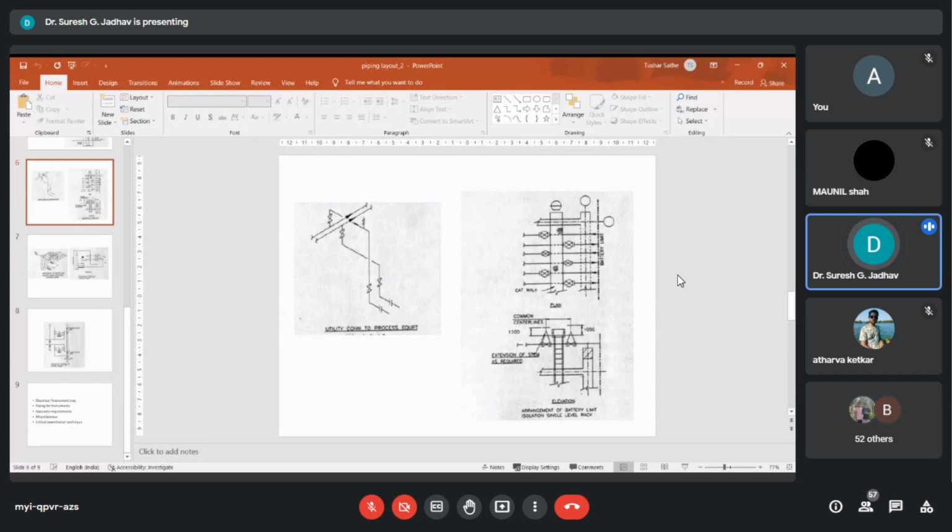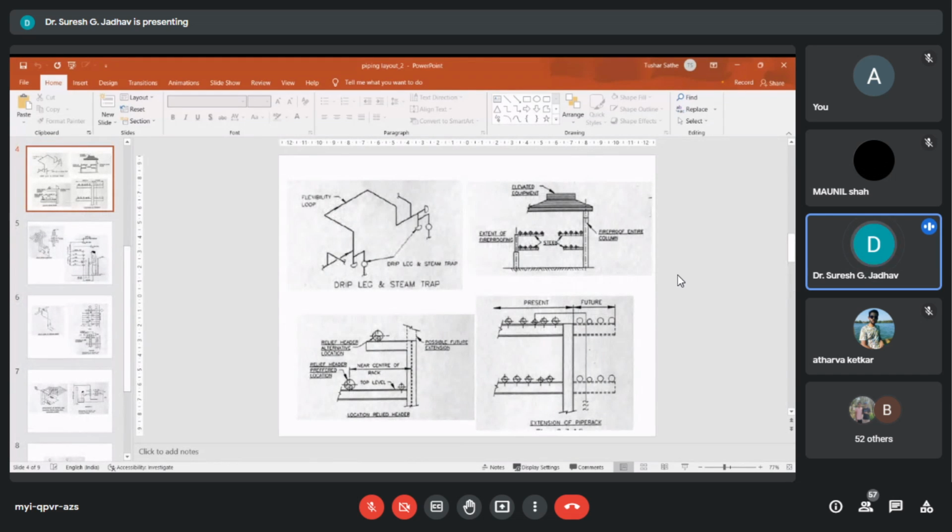So here you can see the piping rack. So here we can provide the electrical and instrumentation trays, where we have to specify the locations, whatever allotted location, including the type of supports. Later we will discuss what kind of supports we are using in the rack, so that electrical and instrument hardware and their supports do not interfere with the operation and maintenance access.